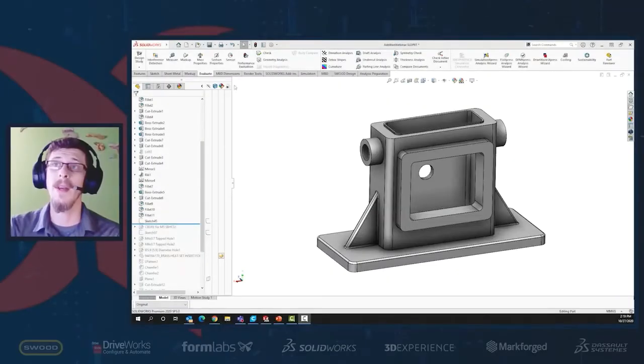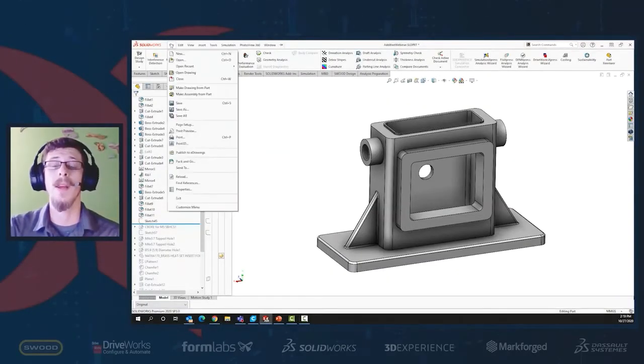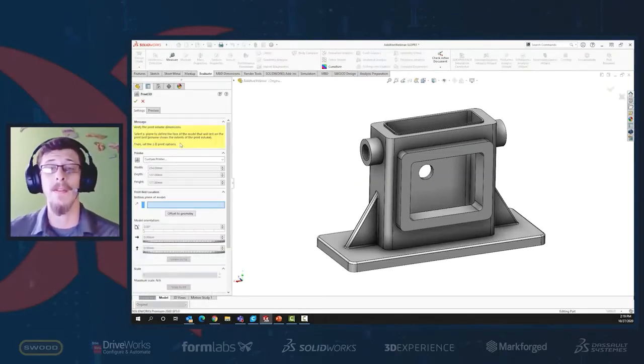As mentioned, it's underneath the File menu. So a good chance is, if you've been using SolidWorks for quite some time now, you've seen the Print 3D, but you've never really tried it. And that's because it's been on the File menu, right below the Print command. Within Print 3D, this allows for us to envision our item within the print bed and see how it's going to behave and its best orientation and how it fits at volume.